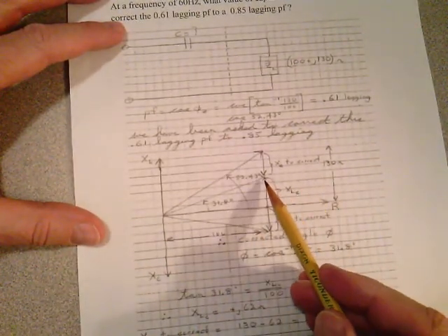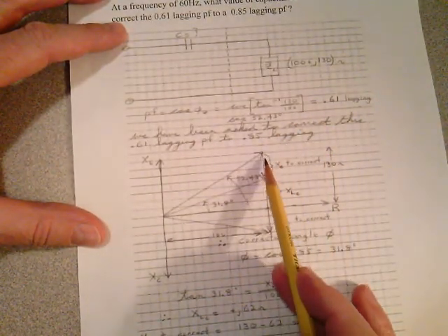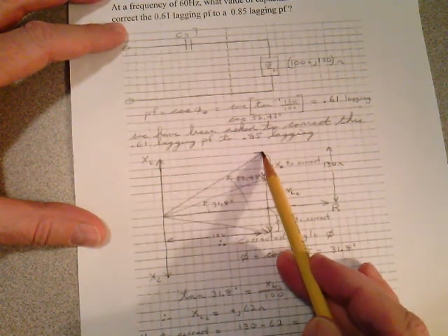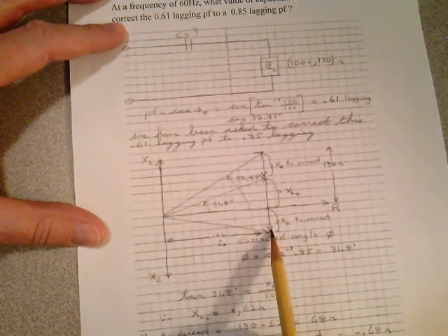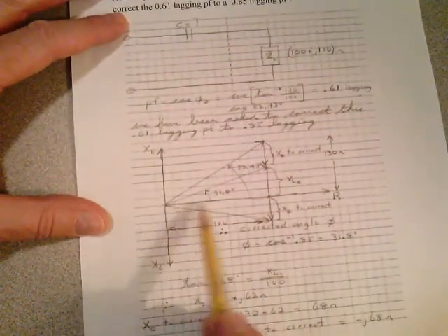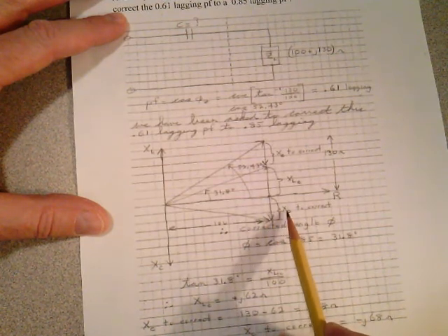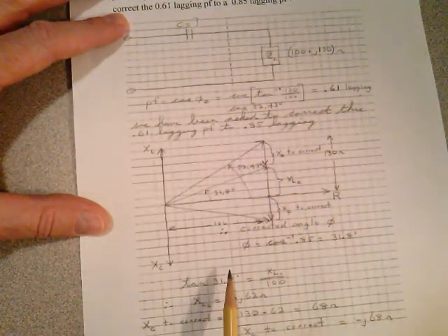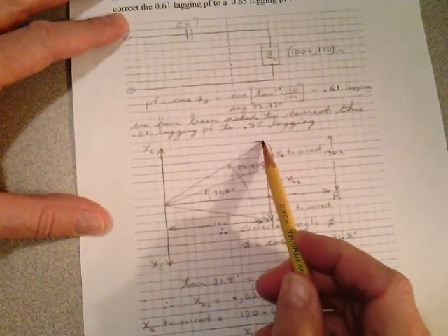Well, to do that, I think you see here that we have to deduct this much inductive reactance. How do you get this point down to here? Well, you add a capacitor. You add a capacitor up here. That capacitor basically puts a triangle down here. So I need so much X sub C, so much capacitor reactance, to offset all this 130 ohms of inductive reactance. Well, how much do I need? I need this much right here. I need from here to here.